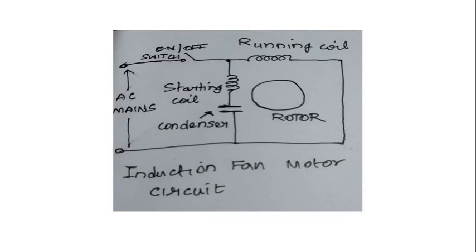If you keep the fan at a particular position, when there is a voltage fluctuation, that is during midnight, the voltage rises, so the fan runs at very high speed which you don't like. These things are common to induction motors as the speed is proportional to voltage square. So its speed depends on voltage also.